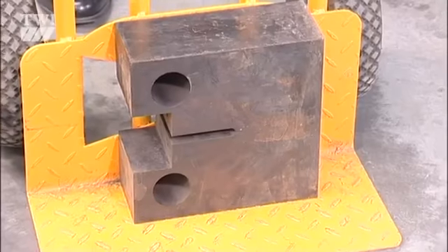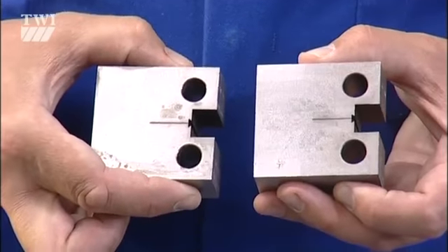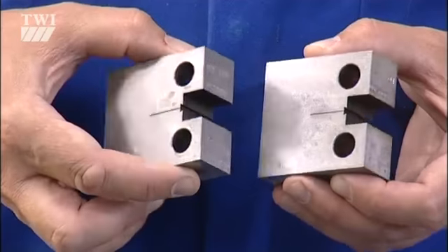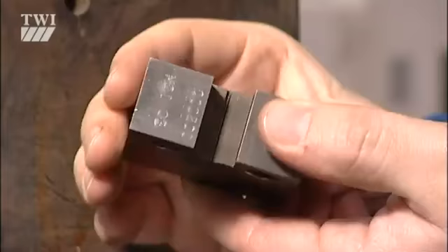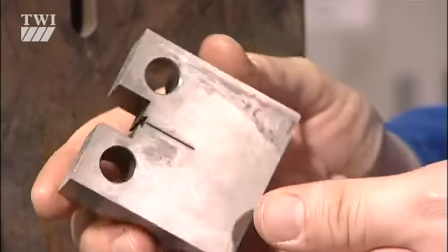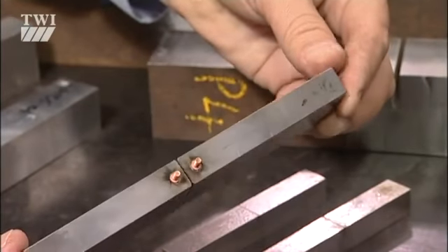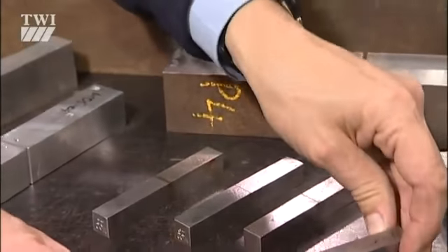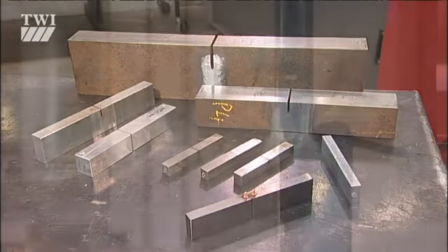It's similar to the SENB specimen in that it's a proportional specimen of full plate thickness, containing a deliberately introduced fatigue crack. CT specimens require much less material to manufacture, but are considerably more expensive to machine. CTOD tests enable critical flaw sizes to be calculated and decisions made about fitness for service, or the required level and sensitivity of non-destructive examination. So they are quantitative tests.